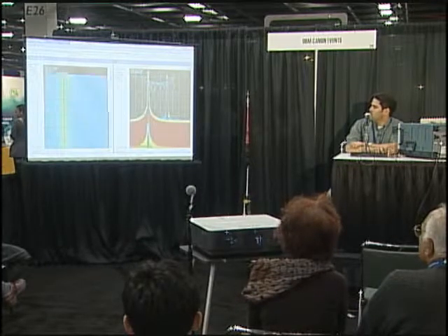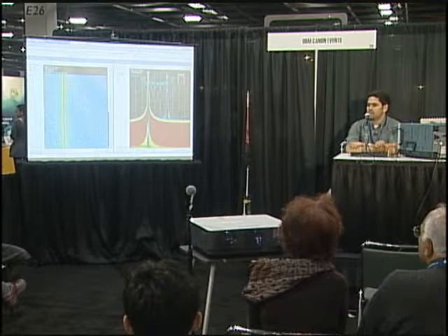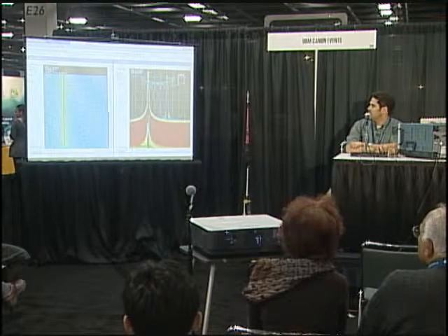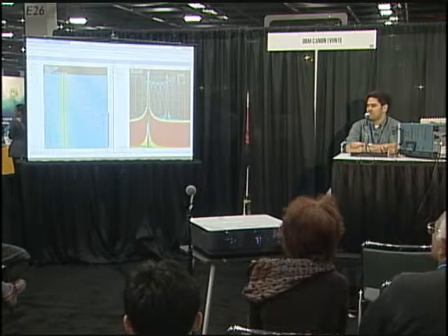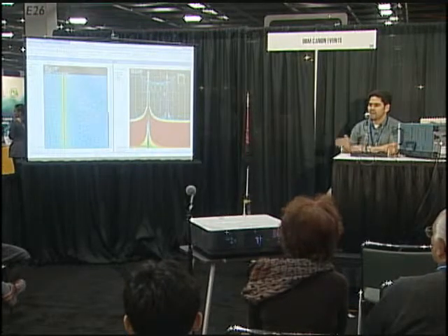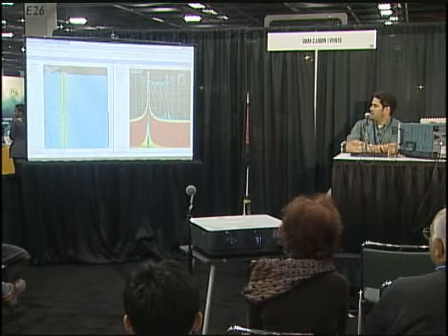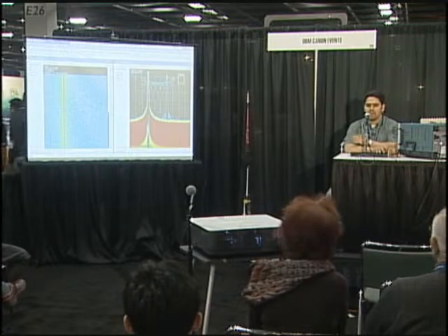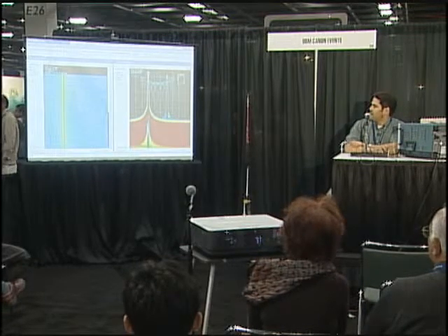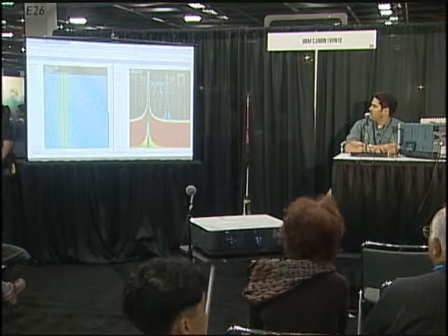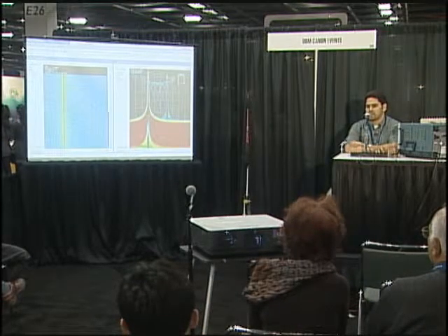All right. So here we see the spectrogram and the DPX display. And we see that this transient doesn't show on the DPX display. And the reason is that the DPX is running in parallel to the main analyzer. And this acquisition engine is also running, they're unsynchronized. So what I want to do next is I want to make these acquisitions when this transient occurs. I want to trigger the acquisition with the occurrence of the frequency event.